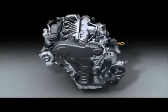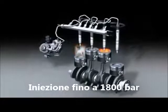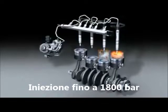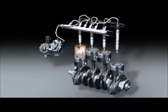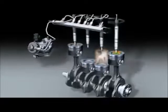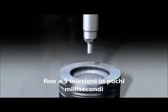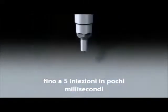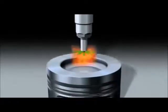The modern common rail system sends 1,800 bar of injection pressure to the fuel injector needles with piezo injectors, which distribute the power optimally in the combustion chamber. Due to the extremely quick reaction time in the millisecond range, up to 5 separate injection processes can be achieved per cycle, which are also variable. In addition to the main injection processes, pre- and post-injection processes are also possible.